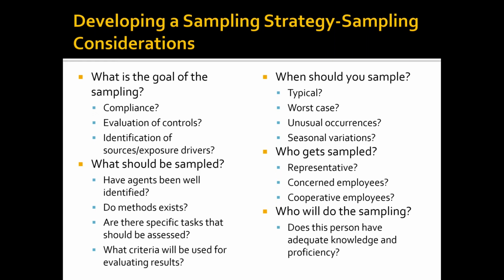When you go into the whens of the sampling, this is oftentimes what I find frustrating as a consultant: you get out to a place and you find out, well, that's not exactly what they thought was happening. And that's very frustrating. So I ask a lot of questions when I'm working with clients about the whens of things. When does stuff happen? When do typical things happen? Are you interested in worst case sampling or just typical sampling? A lot of people want to default to the worst case situations, but however, you need to be prepared to live with that data as well.